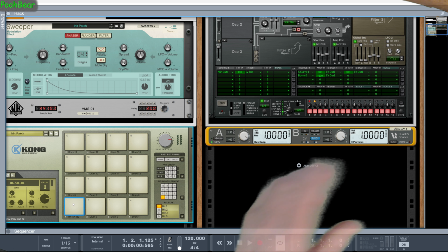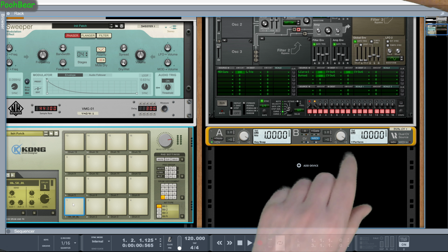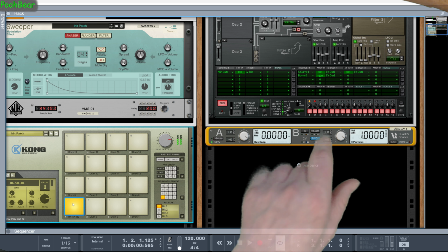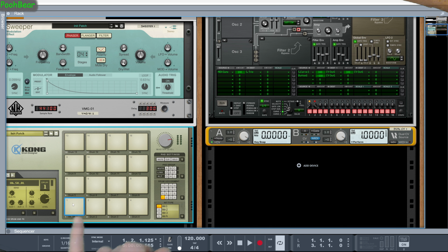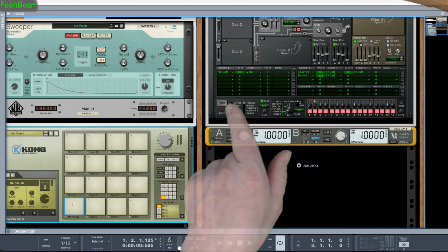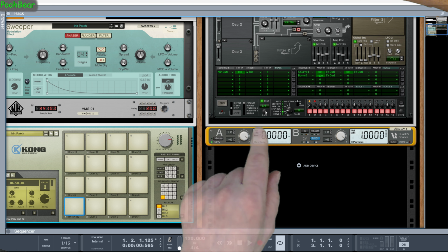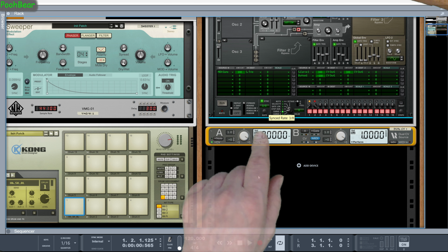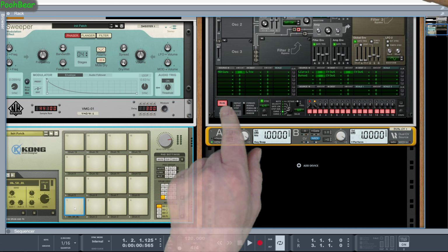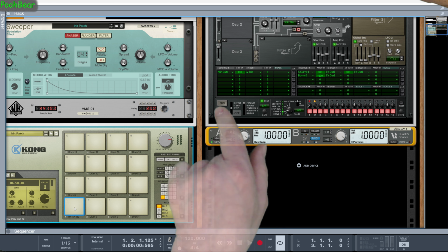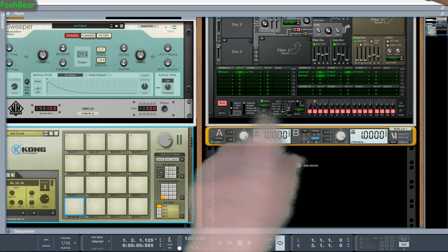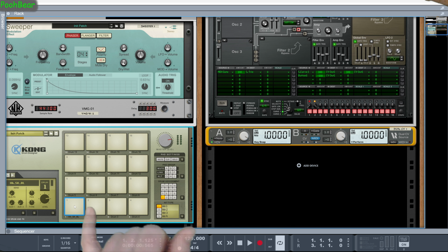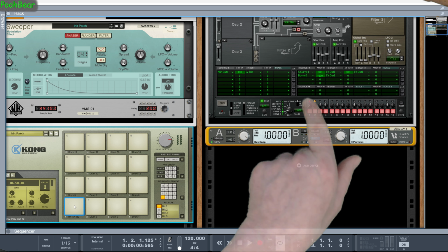Right, so you could hear it. What I'm going to do is press this quite quick. What's actually happening is when I press it, the run comes on, and you can see the run stays on for a little while. This is to do with the sync time. If I go even slower, really slow, and hit it, we can see it stays on. In that time, while that's on, it doesn't matter how many times I press this, it kind of ignores it, and it will stay in that one mode until it's gone off. And as soon as I press it when it's off, it's going to flip back to the other one.